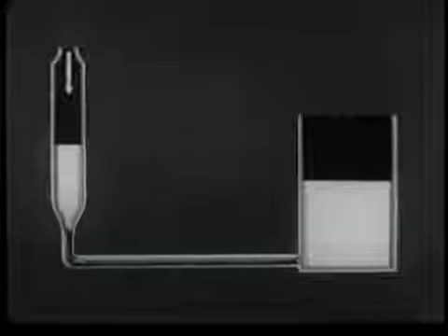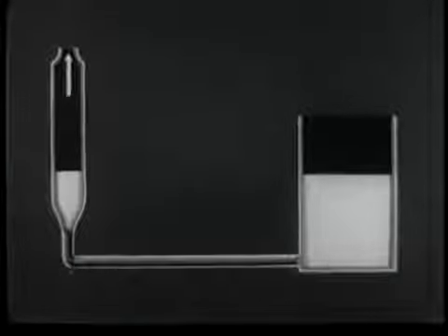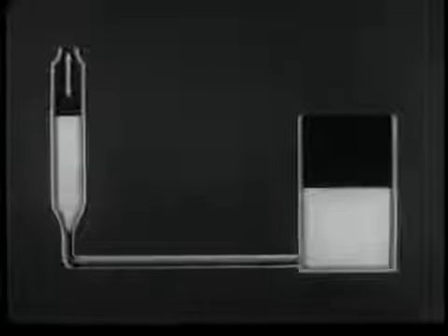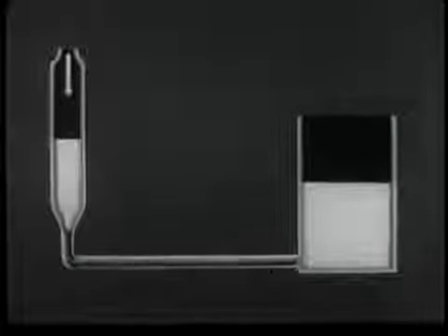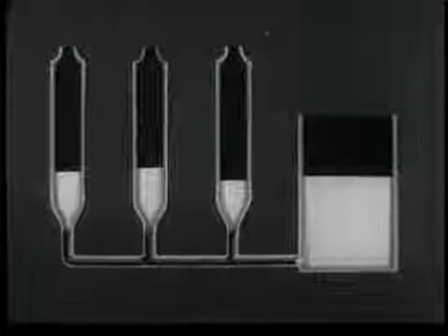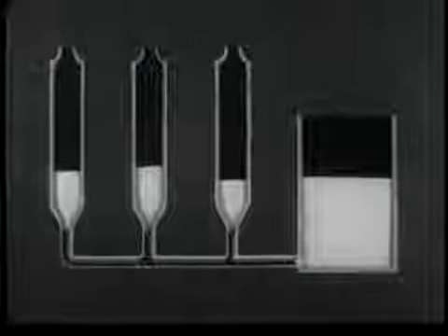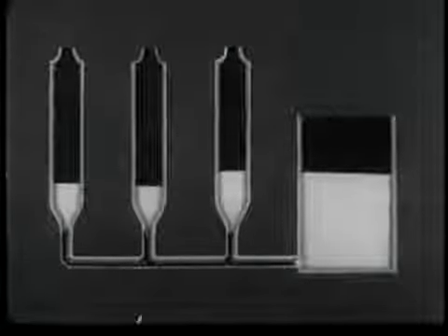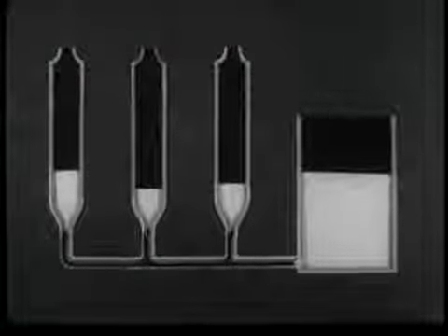In a device such as this, if the liquid in the tube is subjected to varying pressures, the level will rise above or fall below the level of the liquid in the reservoir as the pressure is decreased or increased. Reading of liquid levels provides an accurate means of determining pressure differences. Additional tubes may be added, each connected to a different value of pressure, and each will indicate that pressure accurately, regardless of pressures in the other tubes.